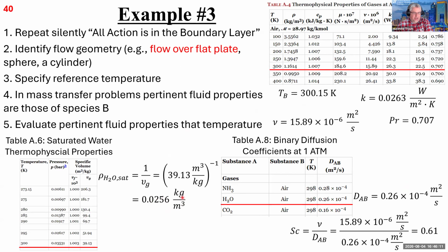That is the concentration of water vapor in air right above the pool, and then far away from the pool, right outside the edge of the boundary layer, we've got the relative humidity times whatever the concentration happens to be, but we're told that the relative humidity is 0, right? So this whole term is 0.